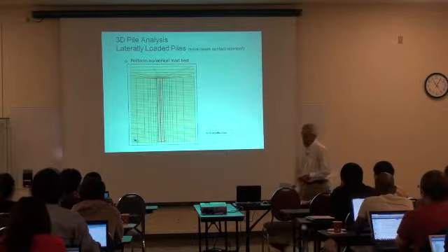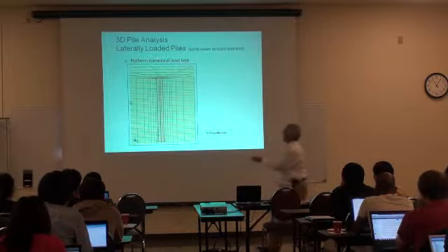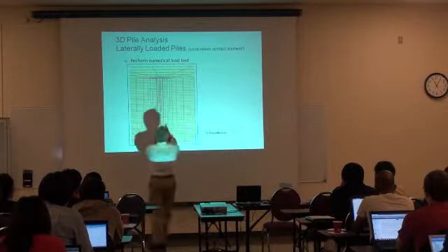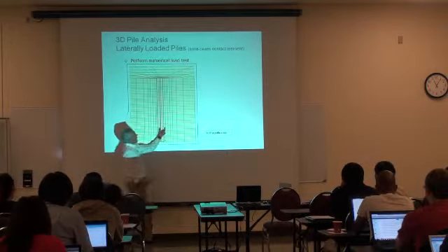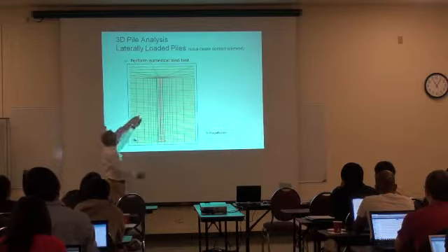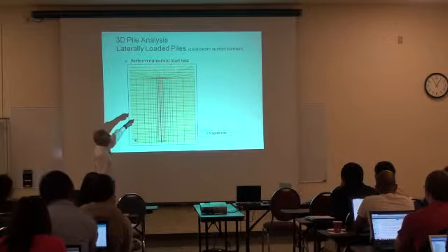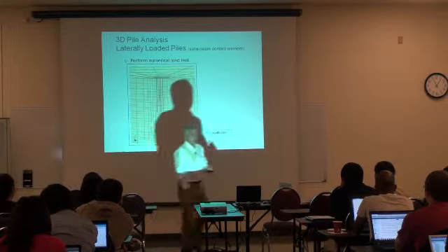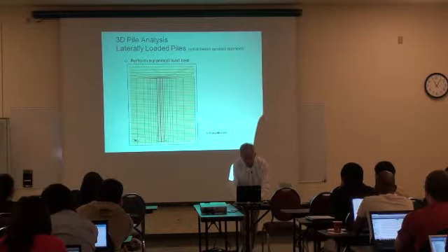Let me show you what happens if I apply a load here at the top of the pile. The beam contact element maintains this gap that represents the diameter of the pile. So if I push at the top, this element of pile is not going to move up to here to start pushing the soil. It's going to push the soil directly as you start pushing from it.